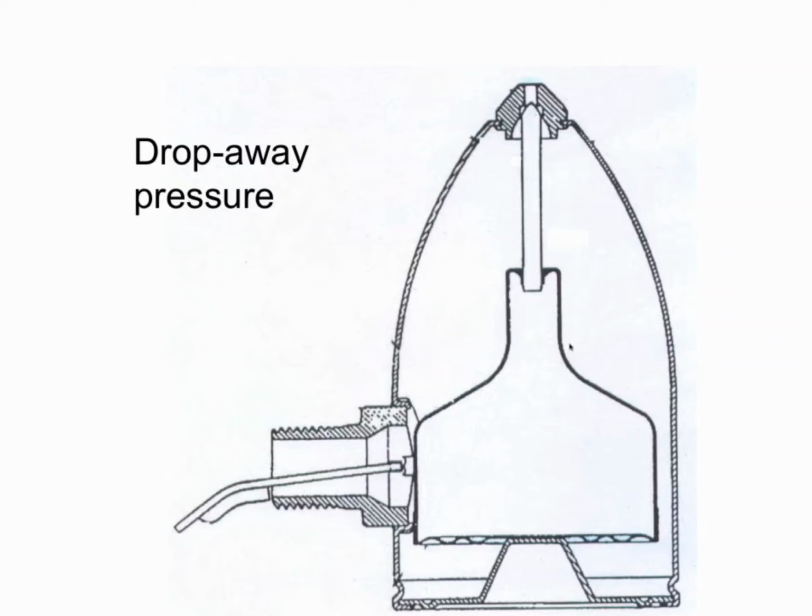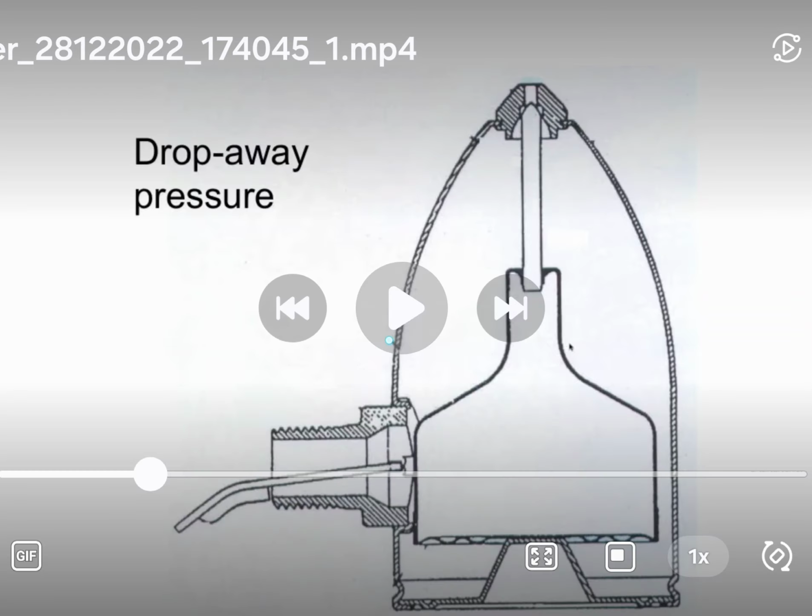You don't have to worry about drop away pressure, not with this particular air vent. Just based off of where you would find it, which would be on a self-standing cast iron radiator, and just based off of how these radiators are constructed and the way this vent responds to their construction, the vent, if it's working as it's supposed to, will not stop venting that radiator until the radiator has sufficiently heated up. And by that time, you don't have to worry about any drop away pressure because the vent has already done its job. So now, with that being stated, let me finish playing what he's saying here. I might even bring it back just so we can get another listen to it.